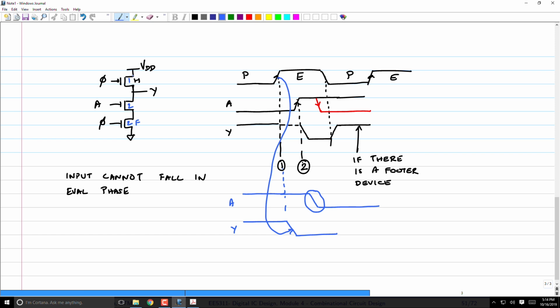Logical effort is some estimate of how long it will take for the output to go high or low, right? But for the output to be high in a dynamic circuit, you have to only look at what happens in this evaluate phase. By the time you are at the evaluate phase, the pre-charge has already taken it high. So therefore, there is no delay in taking the output to a logic high, and therefore pull-up logical effort is irrelevant in this case. It's not zero. It's irrelevant.